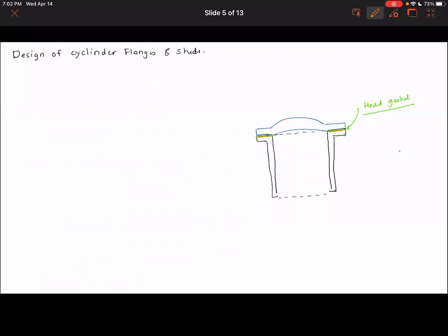Sometimes you will notice that the gasket has warped to such an extent that there are indentations on the piston, or indentations on the cylinder. And at that time, you have no other choice than to remachine the surface. And that is very commonly done in automotive engines. And then actually you refit, so that they provide some clearance for machining the top.